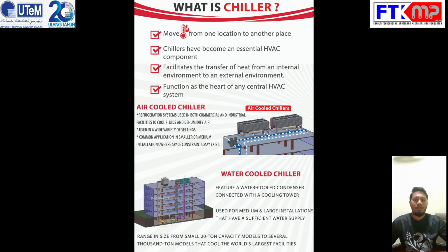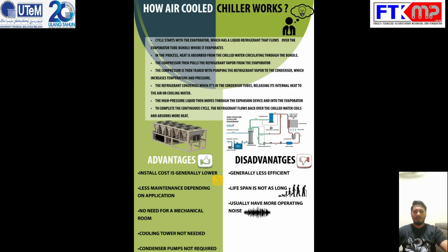Water-cooled chillers feature a water-cooled condenser connected with a cooling tower. They are commonly used for medium and large installations that have a sufficient water supply. Water-cooled chillers range in size from small 20-ton capacity models to several-thousand-ton models that cool the world's largest facilities such as airports, shopping malls and other facilities.